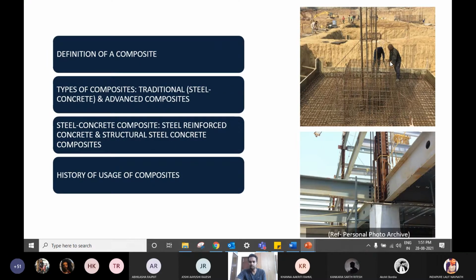The one that you see on the top right is an example of an isolated footing. So we have the footing reinforcement, the mat reinforcement below, and a column pedestal, and column rebars rising above. Right. So this is the foundation of this particular structure, whose picture is down below. This is a part of the superstructure. So basically, its foundations are isolated footings.